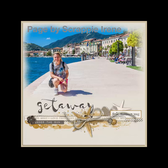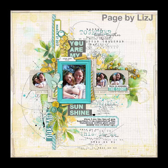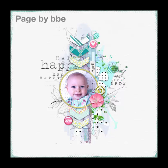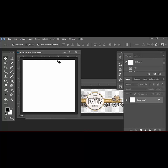When the border you want to use is designed horizontally, you may want to use it vertically instead. Here's how to change the orientation of the border so that you can use it either way. Begin by opening Photoshop or Elements. Open a scrapbook project or create a new 12 by 12 inch document at 300 pixels per inch.